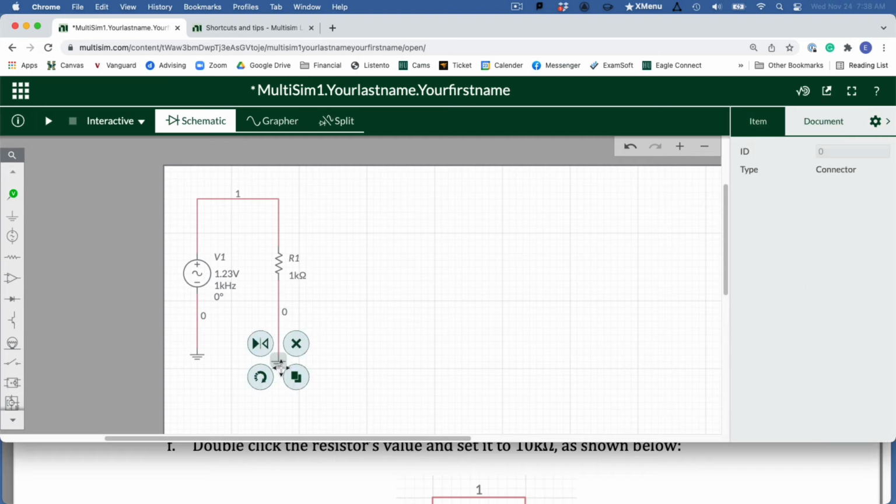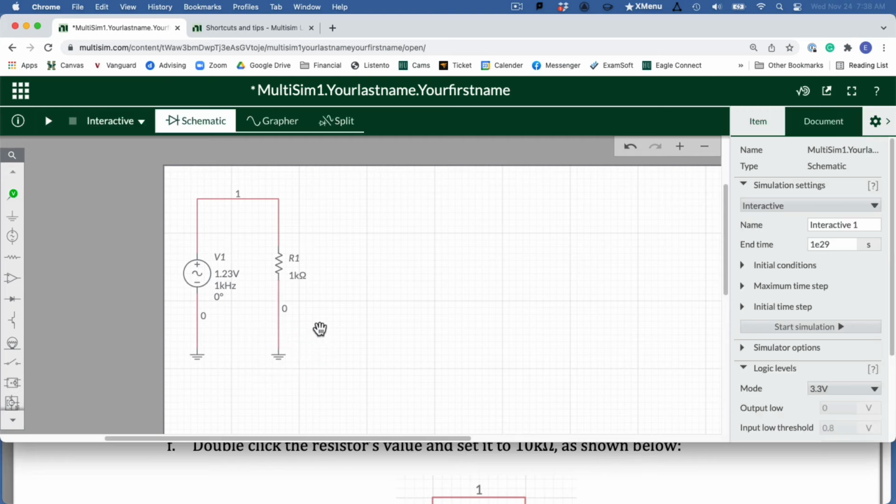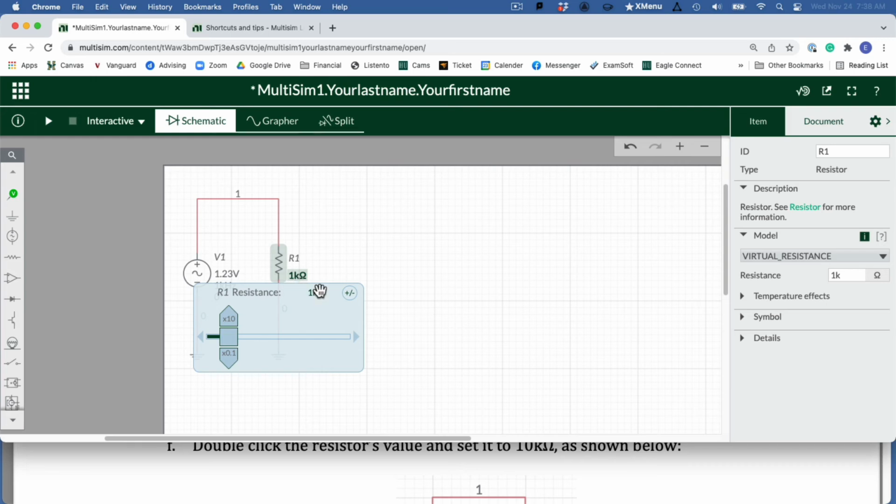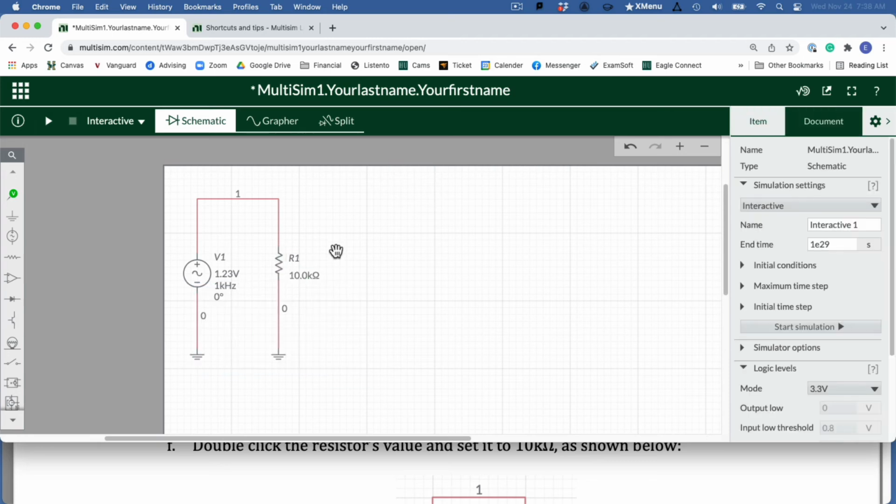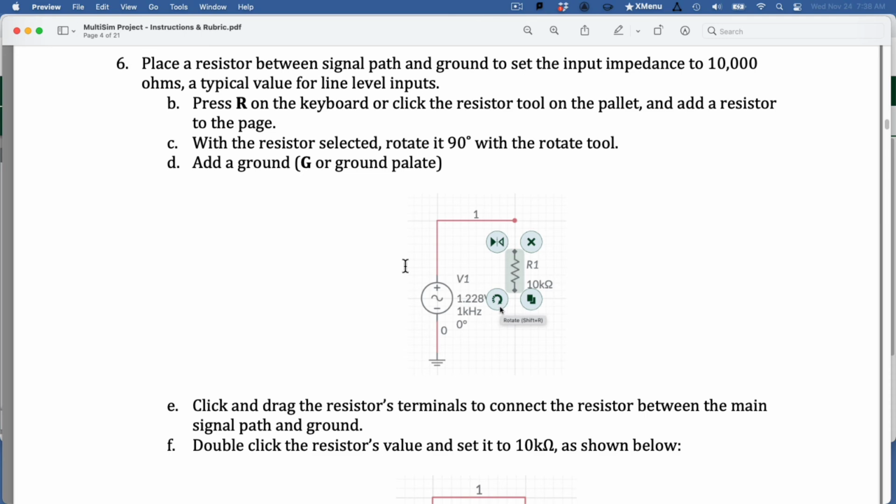And that's 1 kilohertz. I'm anal retentive, so we're going to drag this up here. Kind of matches there. And 1 kilohertz is not the value we want. We want a 10K resistor. So if I double click on the value of the resistor, I could type in 10K, or I could hit the order of magnitude button. Boop, I'm up to 10K. That's pretty cool.